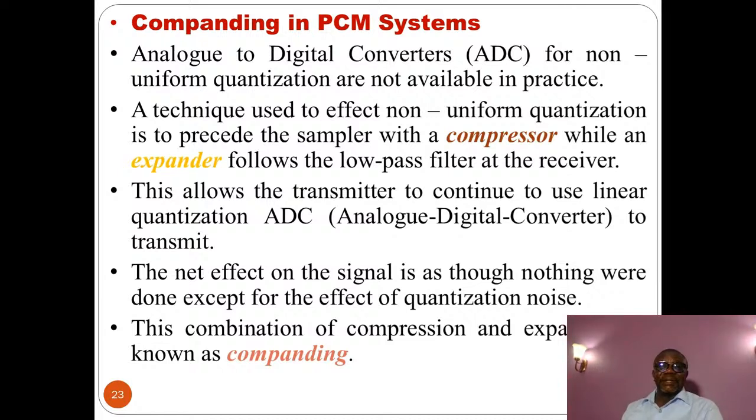So a technique used to effect non-uniform quantization is to precede the sampler with a compressor while an expander follows the LPF at the receiver. This allows the transmitter to continue to use linear quantization ADC to transmit.